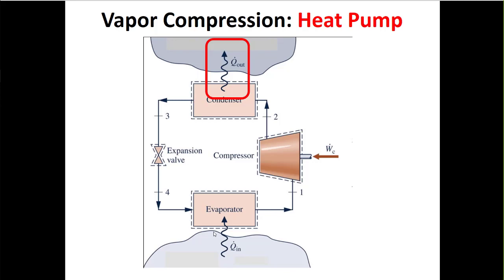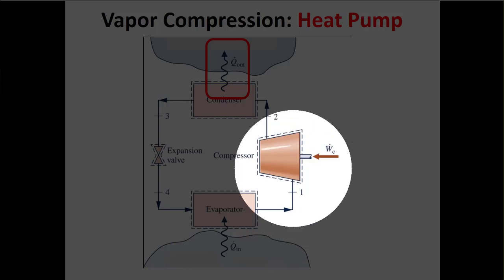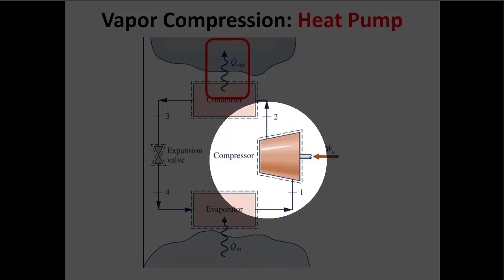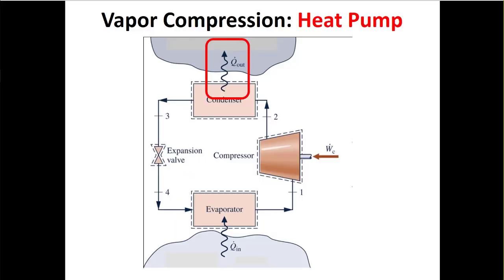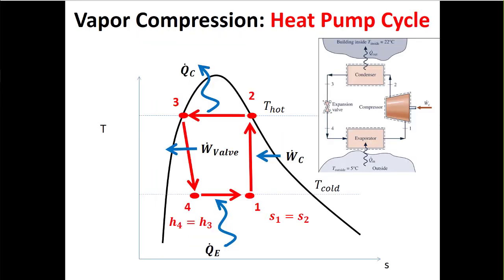And the nice thing is, there's only one component that contributes to net power, and that's the compressor, right? Because this expansion valve, because it's isenthalpic, H in is equal to H out, then m dot times H in minus H out is equal to 0. So it's only the compressor power that matters in the heat pump and refrigeration cycles that we'll talk about in this class. Last class, we kind of drew a TS diagram, right?